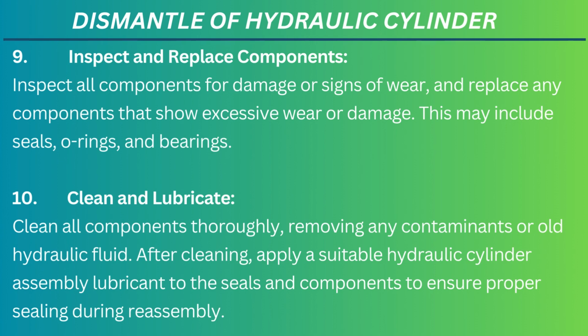9. Inspect and replace components. Inspect all components for damage or signs of wear, and replace any components that show excessive wear or damage. This may include seals, O-rings, and bearings.